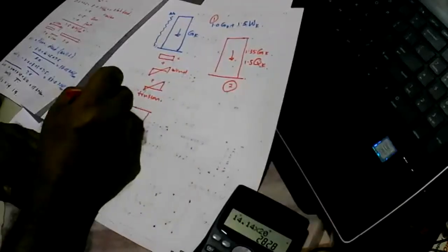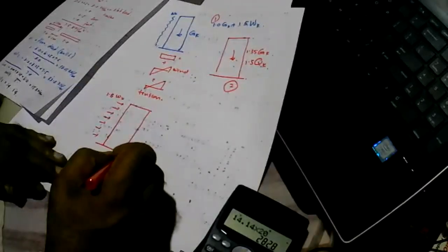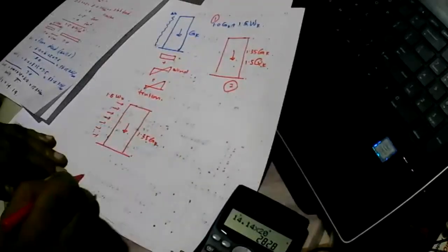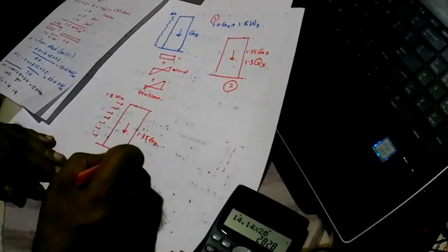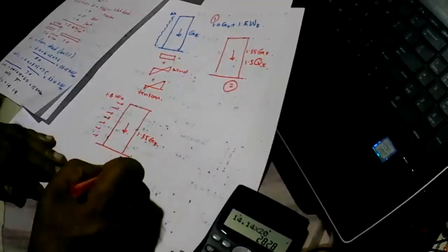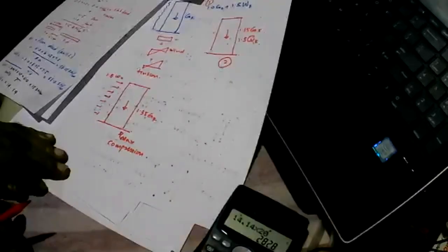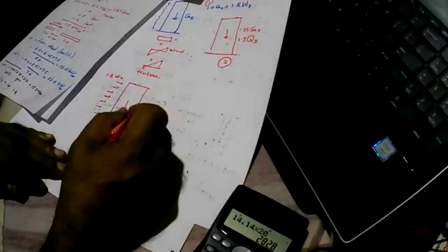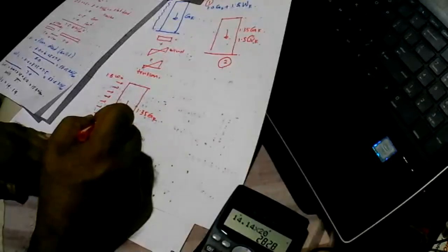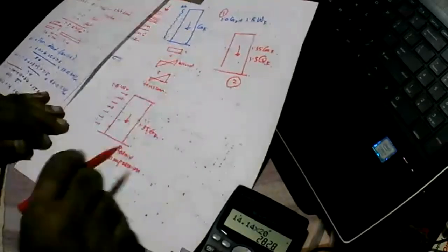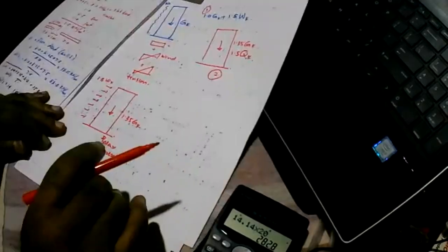and we call it 1.5 times Wk, and the dead load is also maximum, 1.35 Gk. So what happens? We get the maximum compression here. We can get maximum compression here. But because Gk is with 1.35, the chances of tension occurring here is remote. So for tension case, we have to consider this one. For maximum compression, we have to consider that.